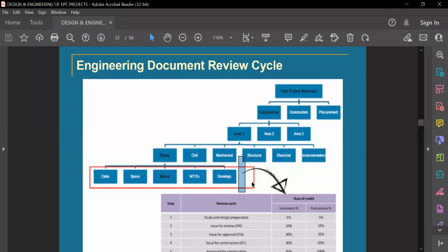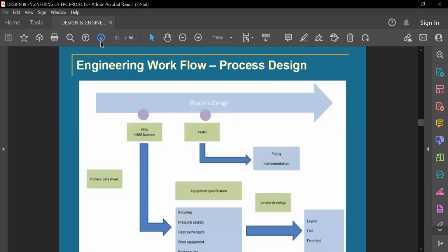One more example I'll give. On the tank I have to do the design of one level transmitter. I have to ask the static people what will be the size of the flange, 2-inch or 8-inch flange. And if any isolation valve is coming, and then valve piping will take that isolation valve, I have to ask them what is the size of the valve and what is the end connection of that valve, so that I can put it in my data sheet and float as an inquiry, so that the vendor can give me a proper interface or proper compatible instrument, so that once it goes to the site, it should be properly installed. So this is our focus, and the cycle is basically on that.